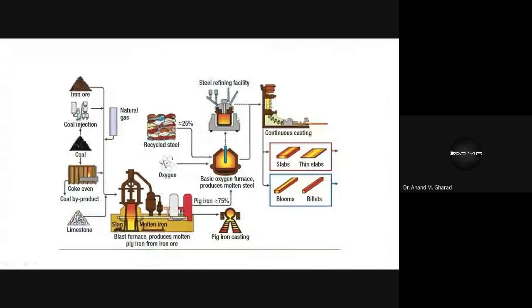We also saw the manufacturing process of steel, and the main component, as you can see, comprises iron ore. Steel is an output of iron, and somewhere you will find the reference of this iron whenever you speak in terms of the grade of the steel. But this is an overall manufacturing process, and the output results may be in the form of thick slabs or thin slabs, just like thick or thin plates, you can say. Then these are known as blooms and billets.